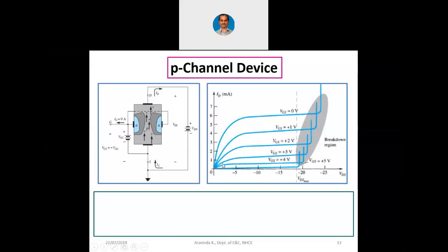Why? Because when the drain to source voltage reduces, it means that the device is completely on, and in the cutoff region, the device is completely off. Why? Because when the drain to source voltage is larger, it simply means that the switch is off. Please recall all the basics of BJT. The same concept is applicable here even in JFET.